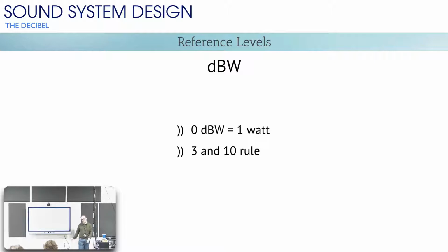and you put that into the headline, and that usually is watts, right? So it's like, this one is 100 watts, this one is 50 watts. 100 watts must be better because it's bigger, right? The 100 watt speakers, the sensitivity on the drivers is way lower. And higher impedance. Yeah, exactly. So it doesn't matter. You might get the exact same actual sound output out of both of them, right? It doesn't matter unless you know everything else. Just saying the number of watts is not giving you a complete picture, right? There's far more going on in there before that turns into sound that you hear.